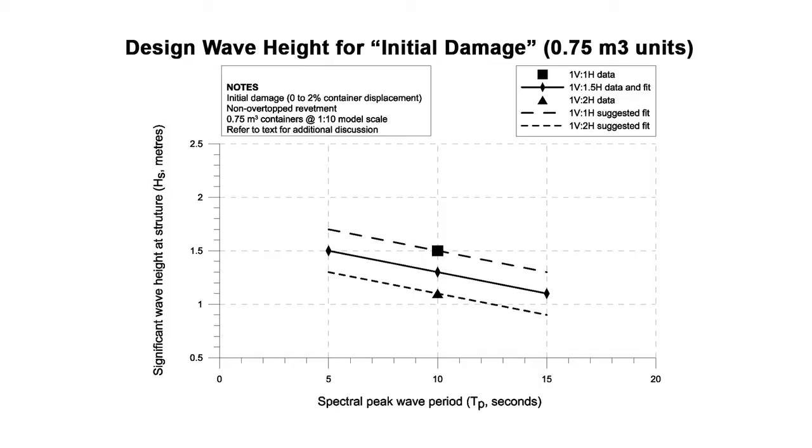So we sit there, run 1,000 waves on the structure, and see how many units have been dislodged. It's 0 for all these different significant wave heights here. So even up to, from our early test, we start with 0.5 metre waves, no damage at all. We crank it up to about 1.3 metres for this case, no damage at all. So there's been 0 units dislodged. Once we get, in this particular case, 1.5 metres, you can see these are all individual tests, these data points. We go above 1.5 metres, we start getting around about 2% of containers dislodged.